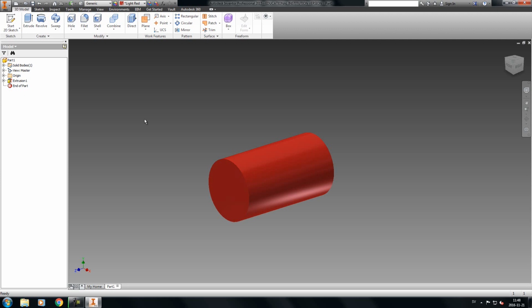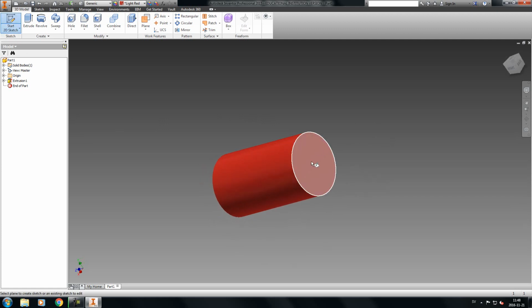One thing to notice when working this way with colors is that it recolors the entirety of the model instead of just a small part of it. This is important to note, as we can recolor small parts of a model later on, but we're not going to do that now. We're going to keep it a uniform color. Now, we're going to make some improvements to this, so choose 2D Sketch again, and click the backside.